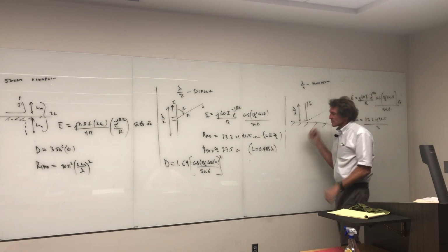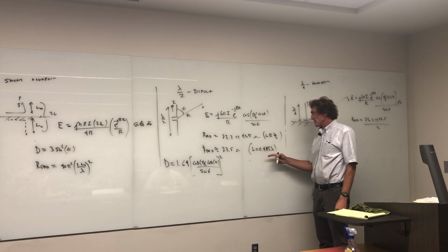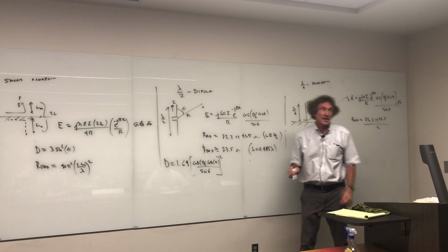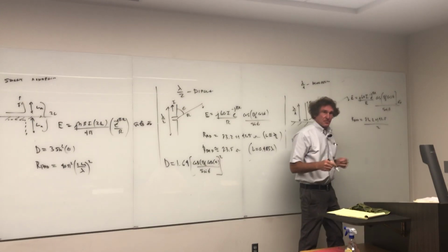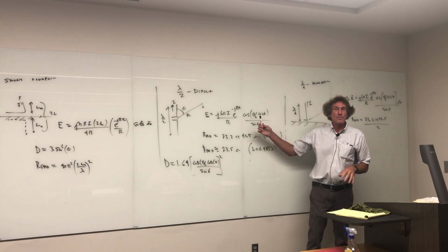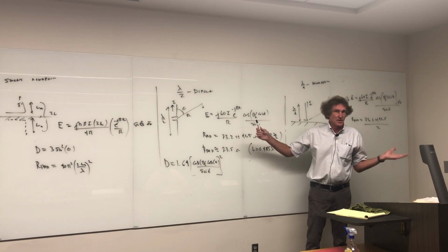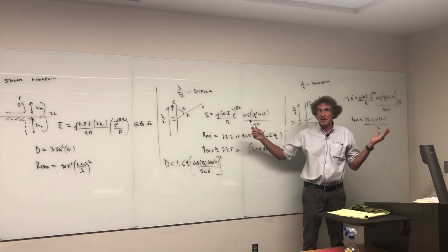And if you chop this one down proportionally, so it's effectively this length by 2, follow me on this, then you're going to get half that. You would get just 73.2 divided by 2 ohms. Follow me, class? In other words, the monopole is identical to the dipole in terms of its radiated field patterns. The radiation resistance is half, the directivity is double. It's the only thing you have to remember.